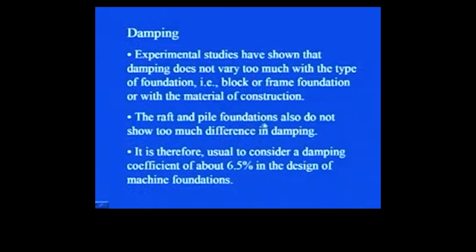The raft and pile foundations also do not show too much difference in damping. So, whether you provide a raft footing or piles as the foundation, it does not make much of a difference to the damping.